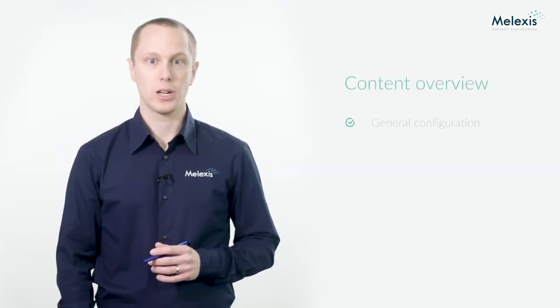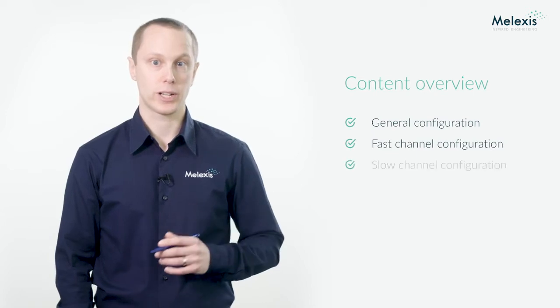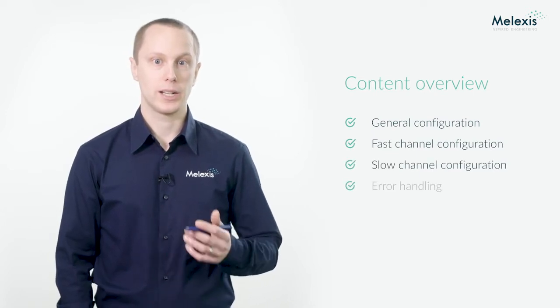I am a Senior Applications Engineer supporting pressure sensors at Melexis. In this movie, I will talk about the SENT implementation of our new MLX90818, a packaged harsh media absolute pressure sensor for 1 to 5.5 bar applications. The SENT output of this product can be configured with a very high flexibility. I will give information on the general configuration options, the fast channel and slow channel configuration, and the error handling.